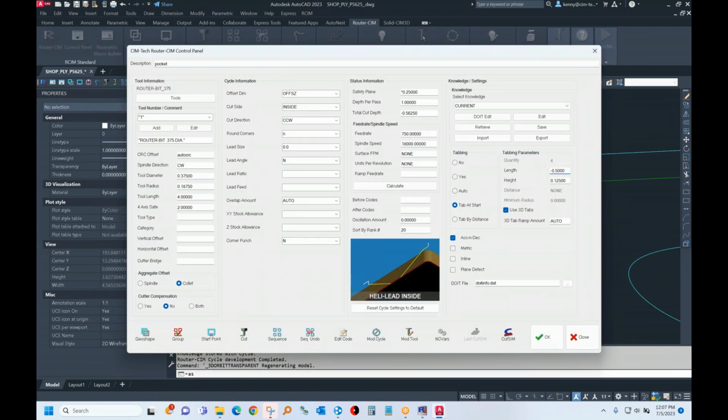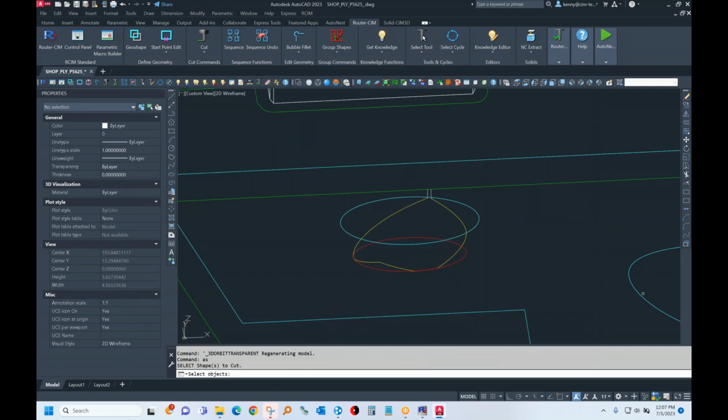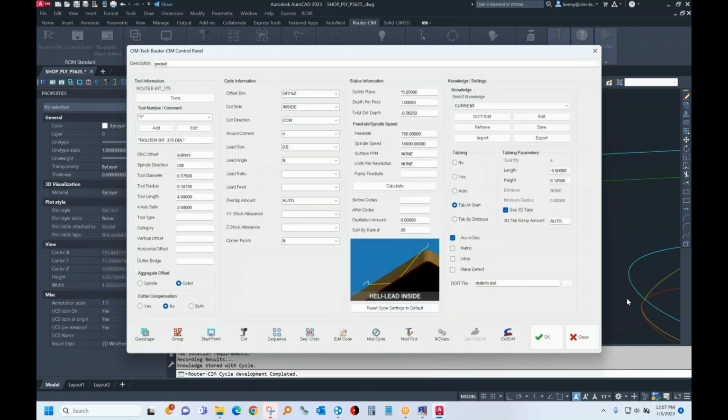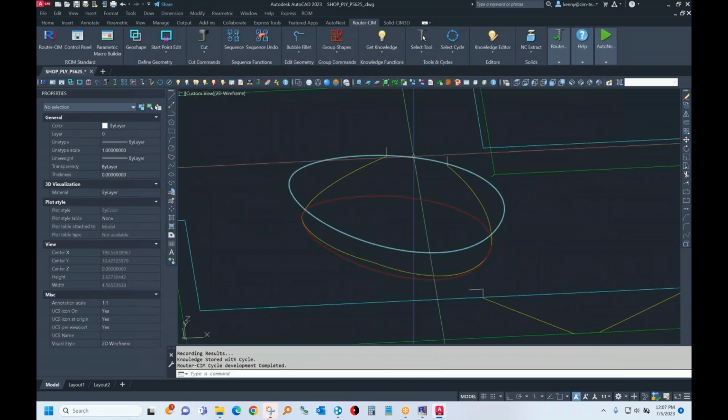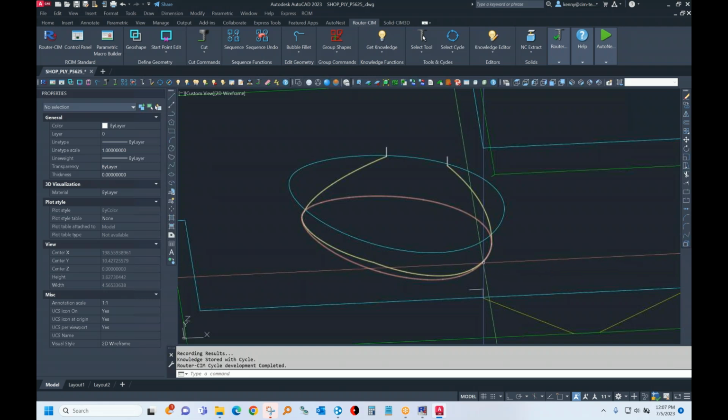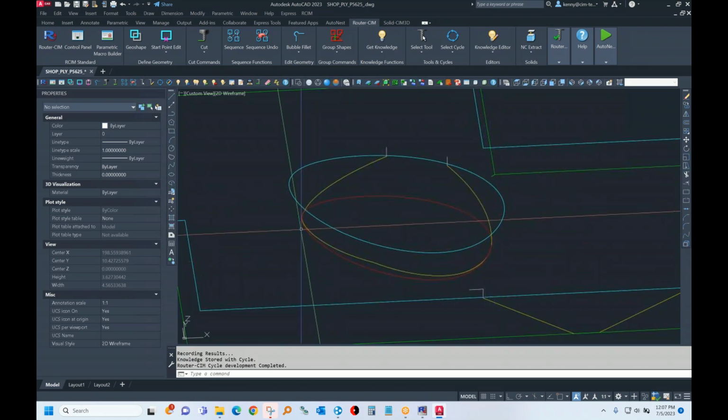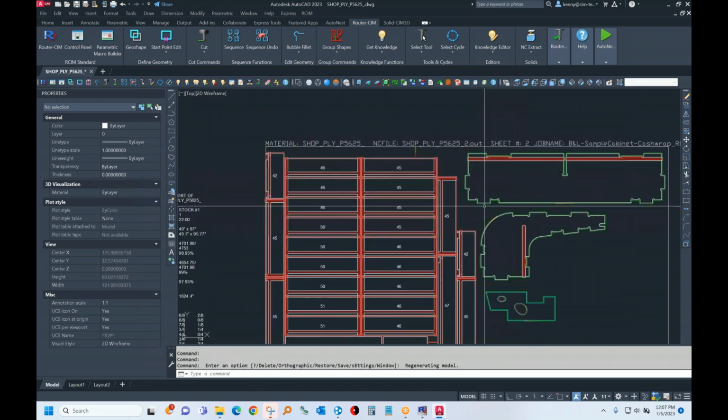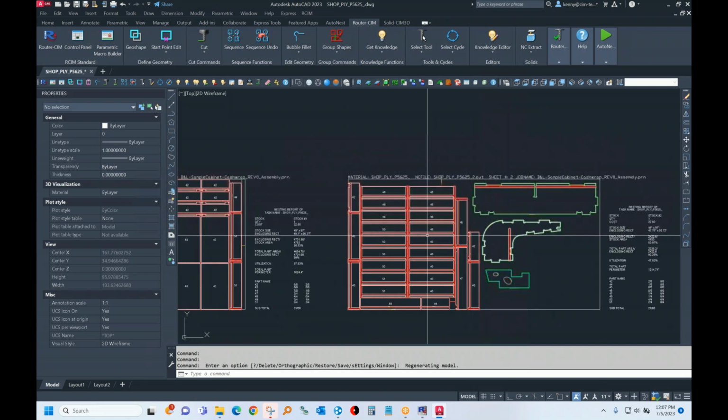Here it is 1 1/2 times, and let's do that on the spline. And you can see, lead in, make a tab that's 50% of the shape, cut around, the overlap cuts it off. It's a great way to save cycle time. Again, you could save cycle time.